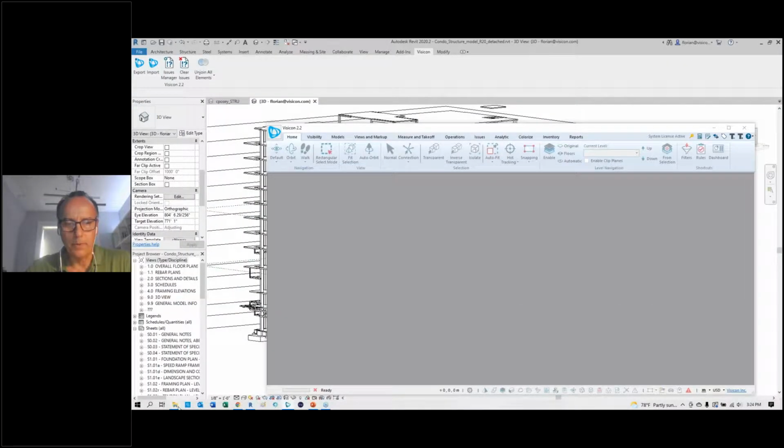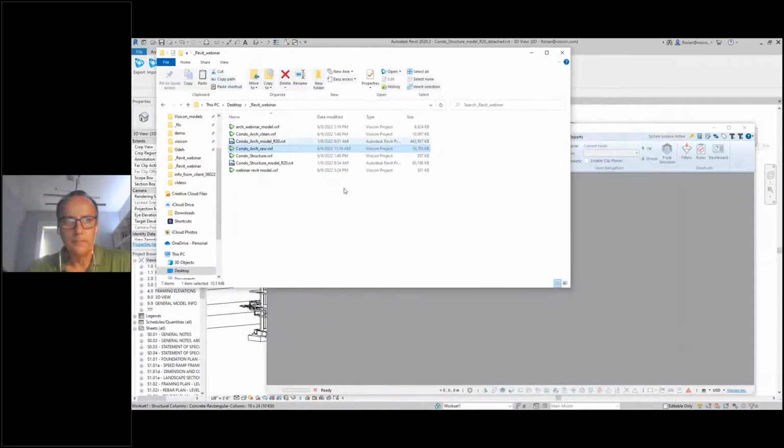We're going to open up our folder. And what we're going to do is take that architectural clean one. The clean one is the one where I removed the boxes and all the extraneous items. Use Control and grab our webinar Revit model. That's the one that we actually created ourselves today. So we're going to drag these two at the same time into here.